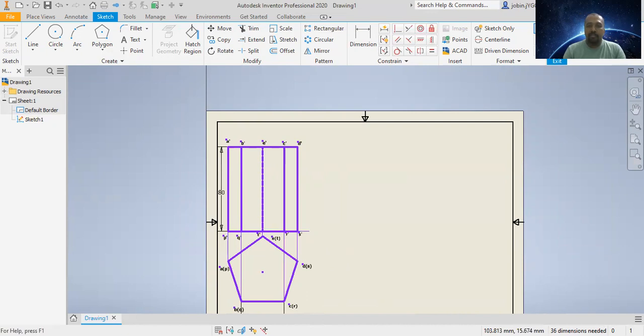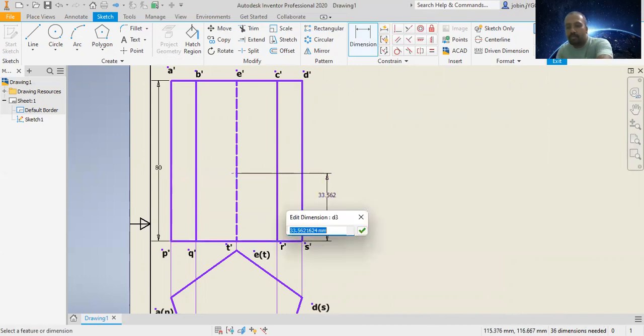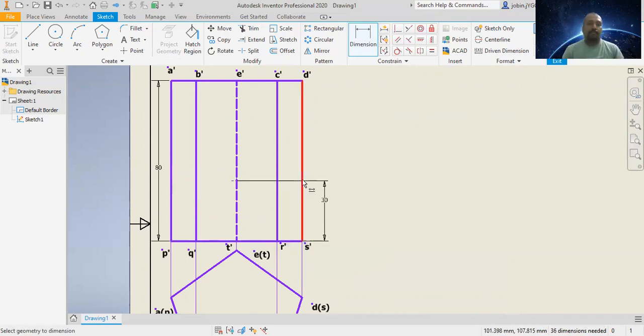Then the next step is we have to draw the cutting plane, the section plane. So 35-degree inclined to HP and passes through a point on the axis 30 mm above the base of the prism. So this line represents the base of the prism. So I will mark a point on the axis, that means the center, such that this distance is 30. From the base, the distance is 30.